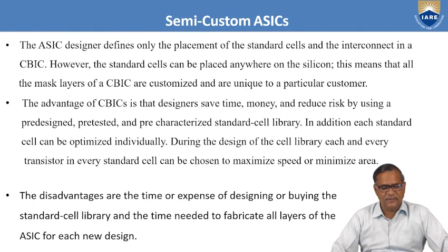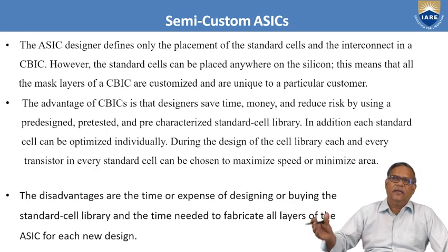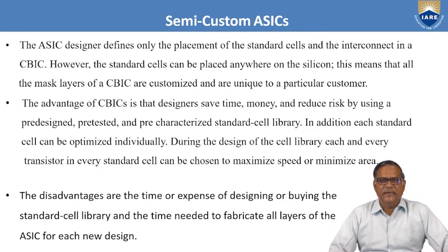What are the disadvantages? The disadvantages are the time or expense of designing or buying the standard cell library, because he is taking pre-tested, pre-designed libraries from elsewhere. He has to buy those cells and it involves money, and also the time needed to fabricate all layers of the ASIC for each new design.